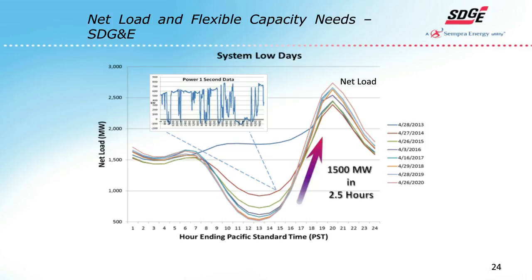Now, a lot of people will tell you that the challenges associated with rooftop solar are really limited to the distribution system, but when you think about aggregation of those numbers into the transmission system, it also becomes a transmission issue. So, for example, we have roughly 100,000 rooftop PV systems today, contributing roughly 680 megawatts. And first off, it doesn't count towards the RPS goals in California. That's just where the rules are.